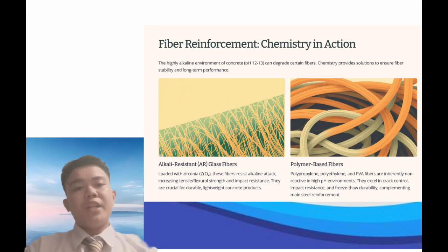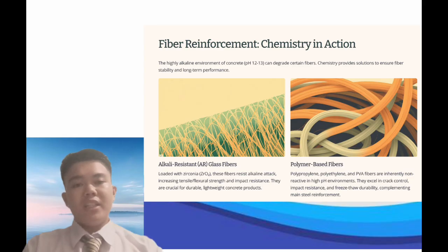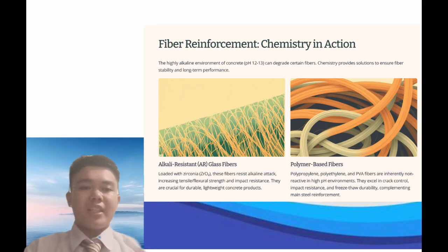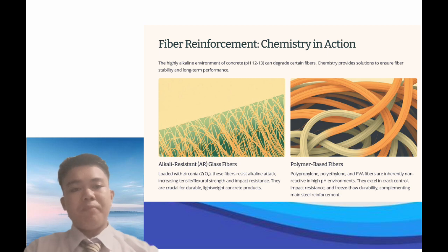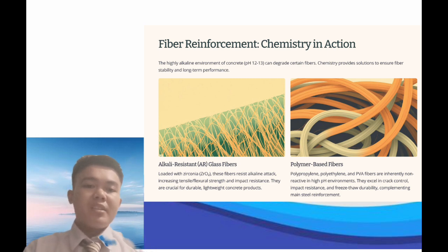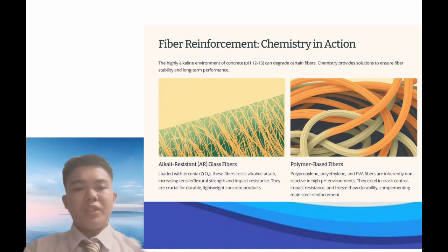Fibers can play an important role in safeguarding concrete due to their alkali-resistant chemistry and crack-controlling processes. Concrete becomes more durable, chemically stable, and better equipped to withstand long-term environmental degradation when fibers are engineered to not disintegrate at high pH levels and to minimize crack propagation.